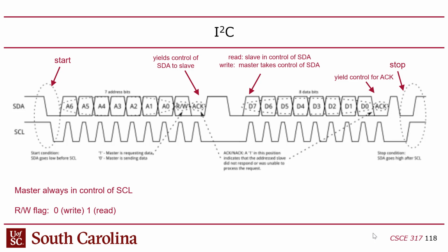Right? So notice how the clock, the way this is drawn, you measure these bits during when the clock is high. Not the edge, it's a level now. We're talking about level sensitive, right? Okay? And so you've got 1, 2, 3, 4, 5, 6, 7, 8 bits, okay? Now, what's not shown on this diagram, well, it is, I tried to call it out there, but basically, once the master gets done with that, the slave, whoever is at that address, has to go into action